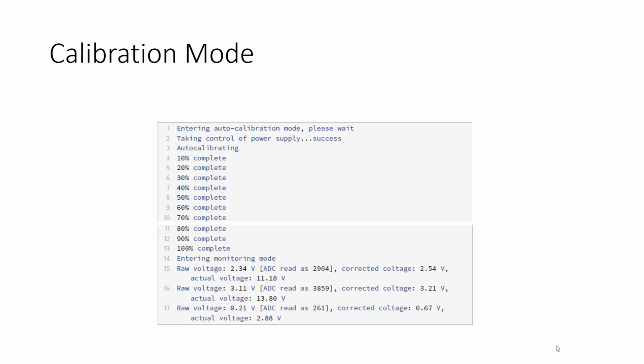The only thing that irritates me about these power supplies is that when they're not enabled, it doesn't tell you what the voltage is. It says 0. Let's say I want to set it up to 3 volts, but I don't want to turn it on yet. Well, you're not going to see 3 volts. It just shows 0. I don't know why it doesn't tell you the set point when it's not actually energizing the outputs. But in this lab, you're just going to set them to 0, then enable it and walk up while it's enabled. You can change it while it's enabled.